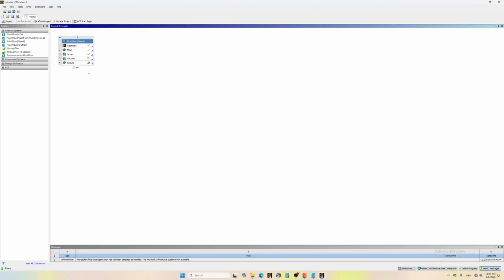So this is the last case that I prepared for a 2D axisymmetric simulation. We will reuse it, so all you have to do is left click here and duplicate. So this will duplicate this case accepting the solution. Alrighty, and now let's give it a name. 3D conical, let's say.